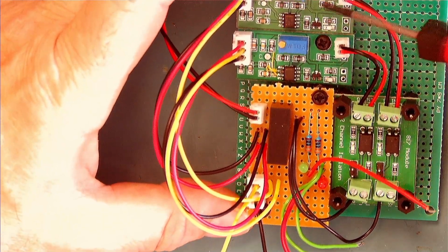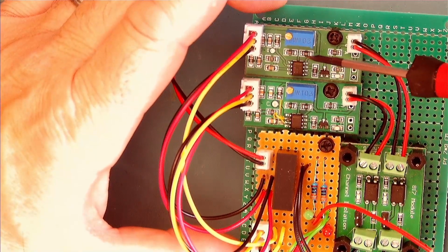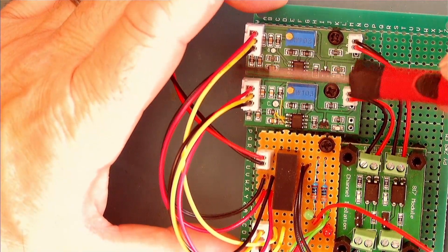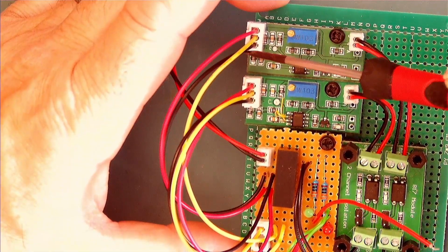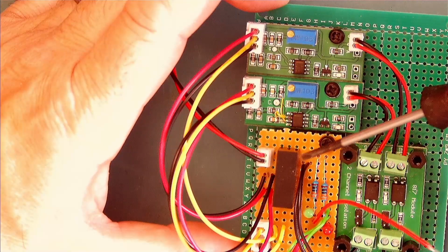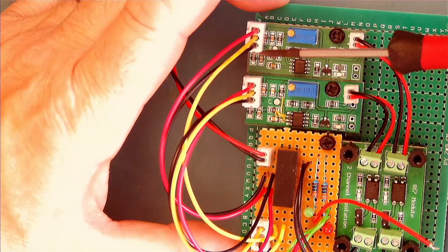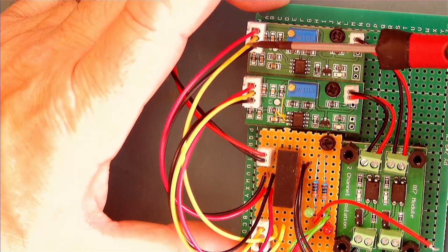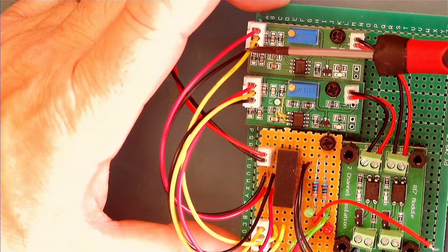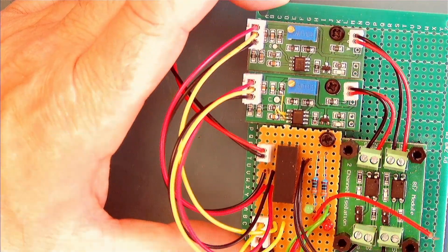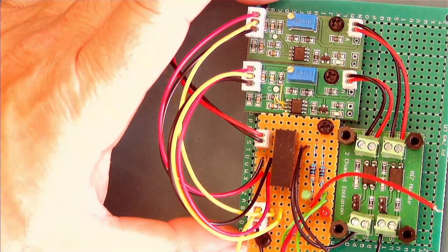As you see, I have actually modified these boards a little bit. I've changed the plugs on them to more suitable plugs for what I want. So I've literally got coming in, this is the voltage in, and the ground, which is coming from the isolated DC to DC converter, and then the actual measurement voltage is on the yellow wire, which is coming basically from this yellow wire here.